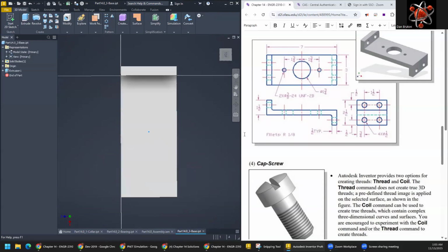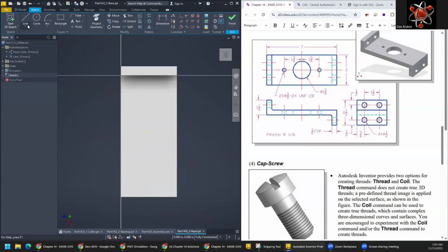We'll start a new sketch on the top just for these 3 circles. Maybe a good idea though is to go back to that practice of making a hidden line right here on the surface. This is going to make everything easier to line up, especially if you lock this one in to the midpoint. And I'm assuming that that's the midpoint, right? Okay, now I can see it's green right there. And this should be fully defined still with the circle.